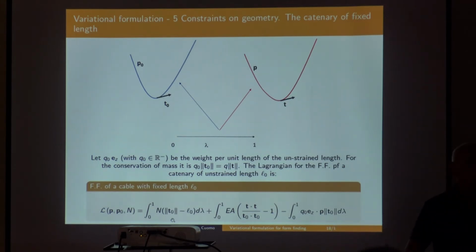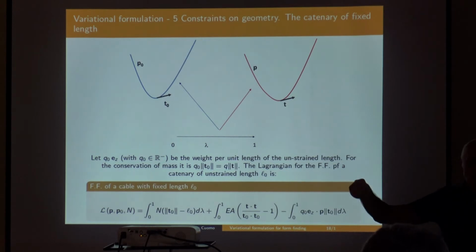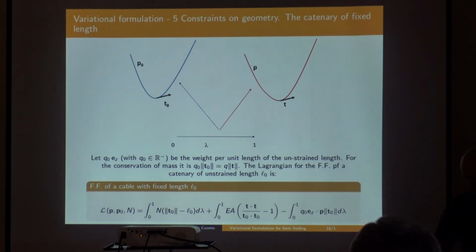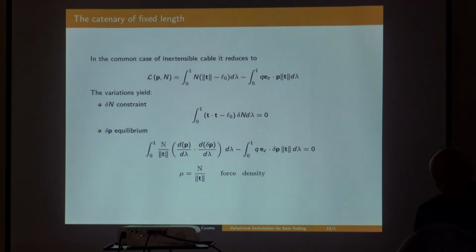And then you may add also elastic energy. In this case, it's possible, because physically you have the cable, you hang it, it stretches, but you can return to the unstretched configuration. So there's no incompatibility in this process, so it's easy to take into account also the elastic deformation. Anyway, in the case of an inextensible cable, the formulation reduces to this one. It is a two-field formulation in this case.